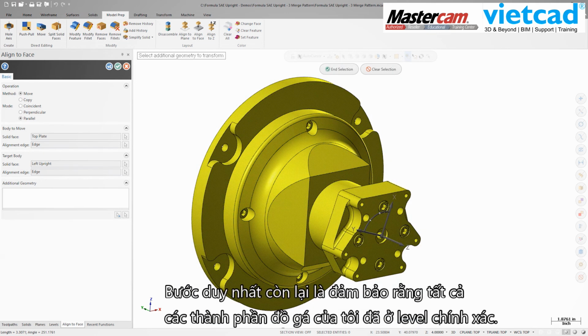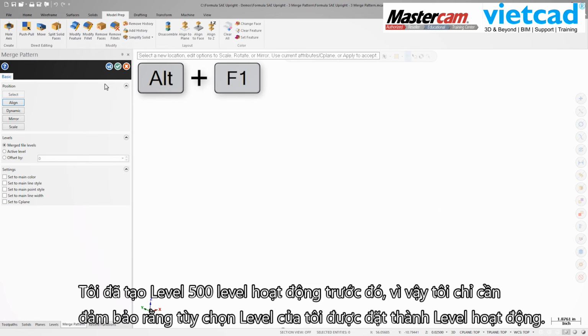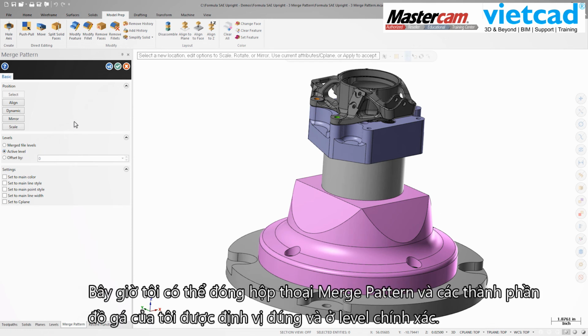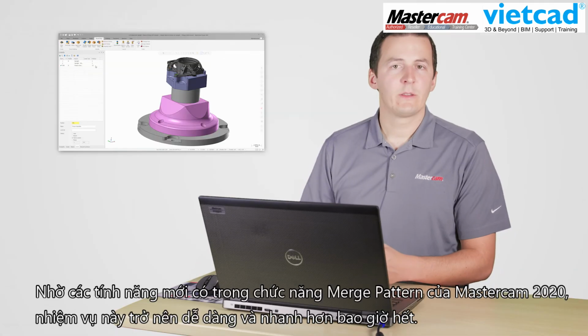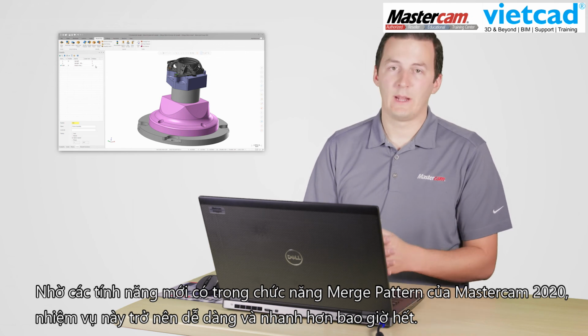I can do this quickly by window selecting the other components as additional geometry. The only step left is to make sure that all my fixture components end up on the correct level. I made level 500 my active level earlier, so I just need to make sure that my level option is set to active level. I can now close Merge Pattern and my fixture components are properly positioned and on the correct level. Thanks to the new features included in Merge Pattern for Mastercam 2020, this type of task is easier and faster than ever before.